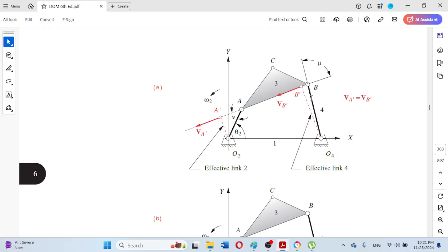In a similar manner, this angle and the line of the rocker link is also the angle of transmission, but the angle of transmission must be less than 90 degrees, as already explained for the angle V between the input link and the coupler link.